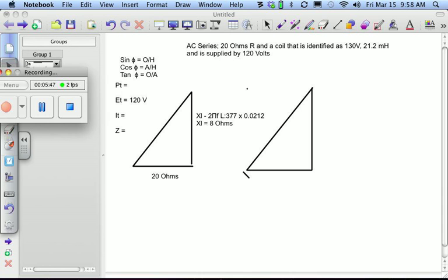If we multiply that times 100 to get a percentage, we get 92.84%. Does everybody agree with that? That's our power factor. So now we know that this circuit is turning 92.8% of its incoming power into true power. It's a fairly efficient circuit, in other words.